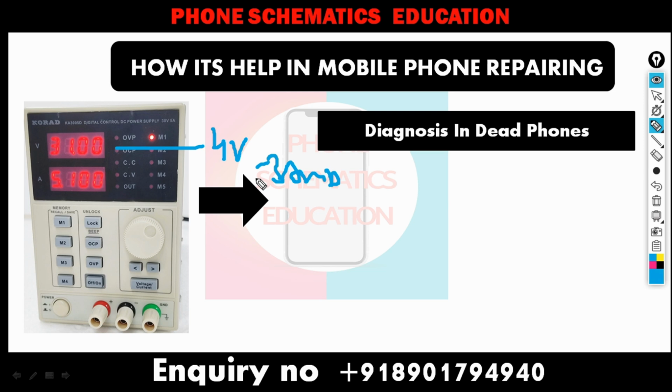First, whether the phone is off or on without the battery, obviously. Also, whether there is a fault in the motherboard or the battery. Also, look at the current, or you can say ampere sequence. We get a clue, or you can say direction, whether the fault is in the CPU, power IC, a power rail, or secondary lines. So we get an idea, so we can work on it. I hope this is also clear to you.